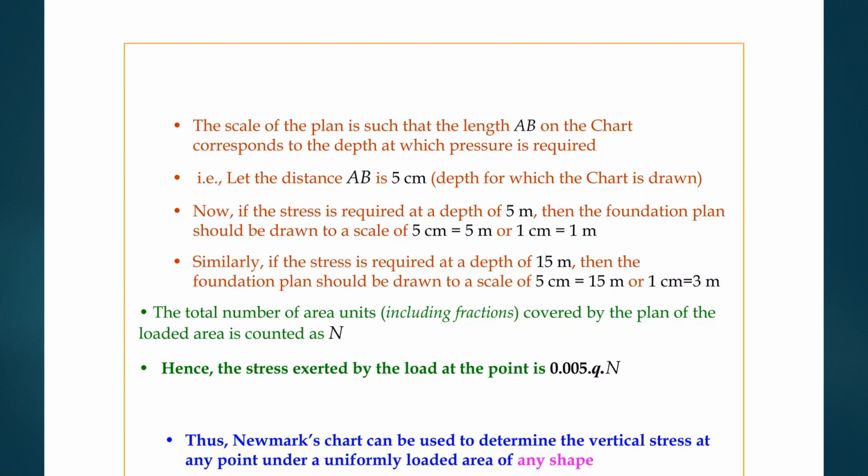Now, if the stress is required at a depth of 5 meter, then the foundation plan should be drawn to a scale of 5 cm equals 5 meter, or 1 cm equals 1 meter. Similarly, if the stress is required at a depth of 15 meter, then the foundation plan should be drawn to a scale of 5 cm equals 15 meter, or 1 cm equals 3 meter.